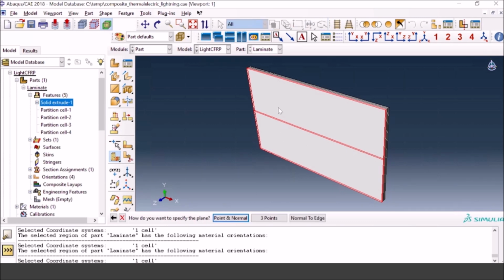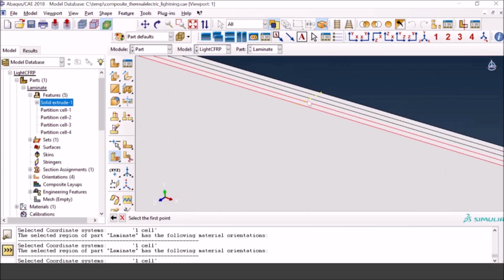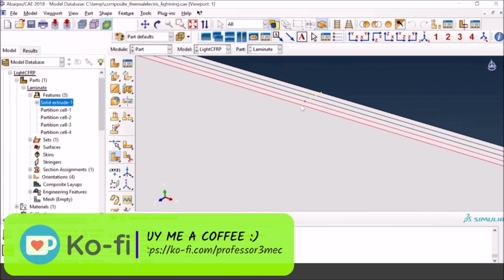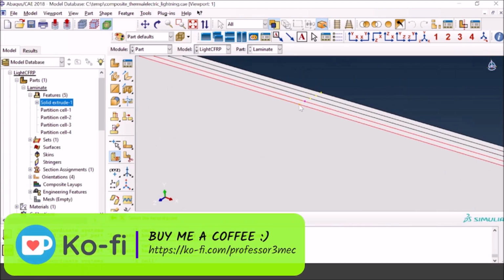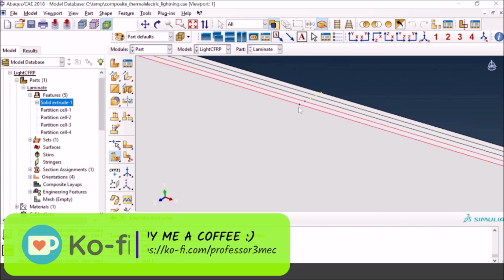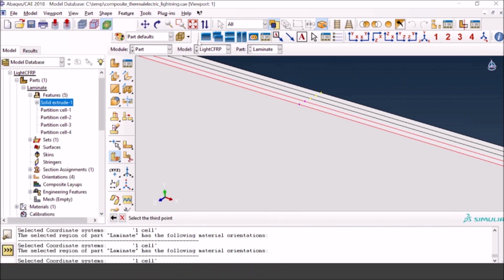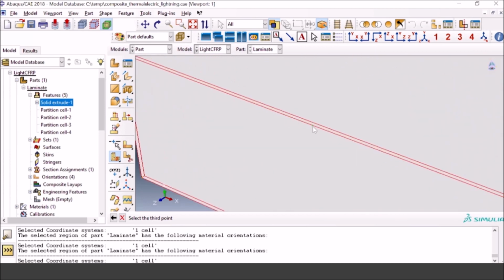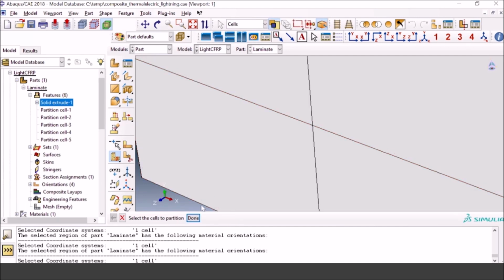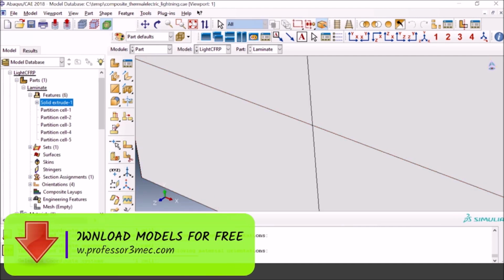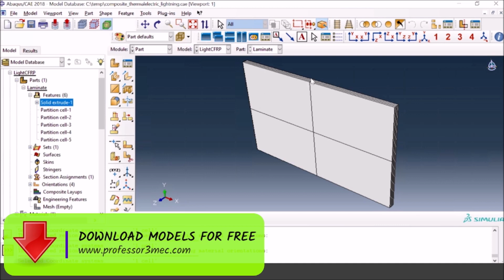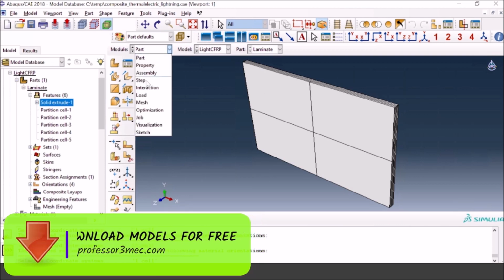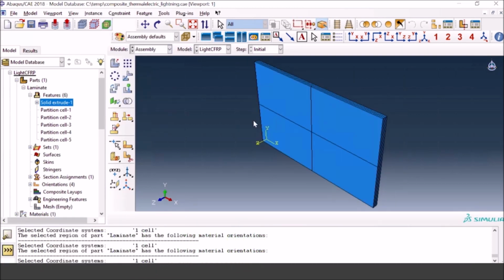So now I will do the same normal to the previous cutting direction, and in this case I will select this point, second point here. And if I can zoom out, I can select anything related to that. Yeah, this should be fine as well, maybe. And that's pretty much it. So now we have the plane and we have a point there where we can apply any loading if it's a point load, which is the case in our present scenario.